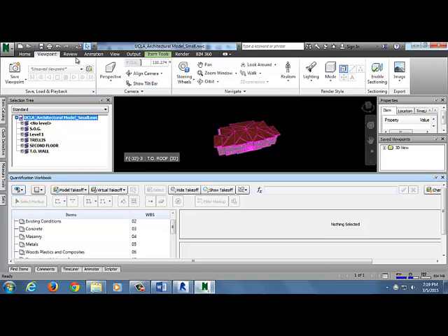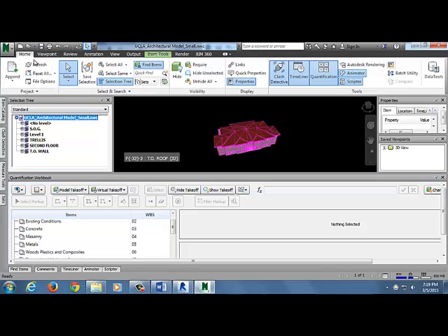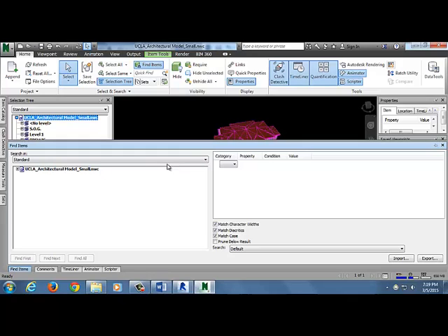I'm going to create a selection set. Oh, my find items is already open somewhere. So the sets are already getting updated, like what we did see here, that we export from Revit, both models, we export to NWC, and then we want to find the sets.